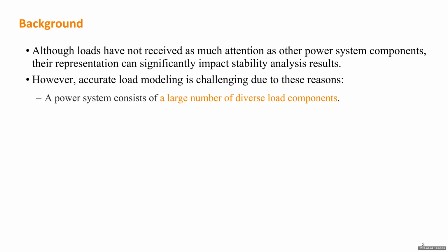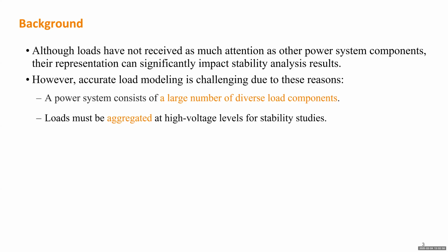But for stability study, we focus on the bulk power system, mainly at the high voltage levels of the system, including generator, backbone transmission system. But loads are connected not at high voltages, they are connected at the distribution voltage level. So we cannot have the accurate details of all the load components. So we have to aggregate all the loads to the high voltage level for stability study.